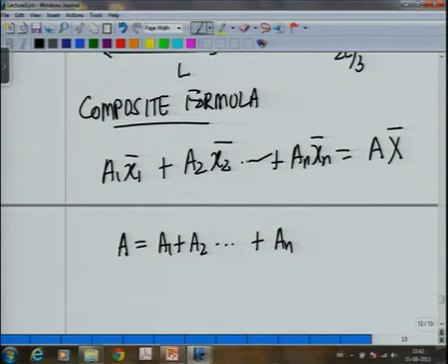Then the total centroid of the total area can be given as A times x bar is equal to this. And this goes even if we have to work out for 2 or 3 components, we can do it along component basis. In this case, of course, all the forces are acting along the same direction. So, there is only one formula for a linear load, but we worked it out like this. Okay. So, now if you have a trapezoidal load, a trapezium type of load, that means you can use this formula.